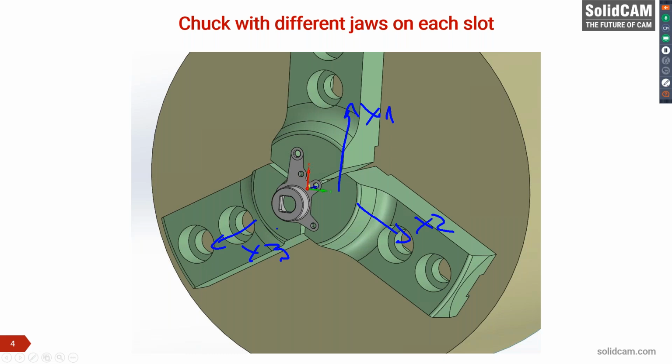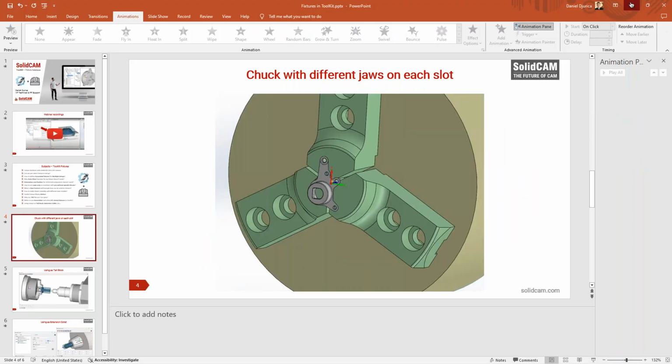I quoted it, you didn't see it, is that you can define a chuck axis through the axis control. So what is the chuck axis? The chuck axis is the specific virtual axis, we call it, that takes into account the reference point on the jaw to calculate the clamping diameter. So let's take a look how you can use both of these and define it inside SolidCAM.